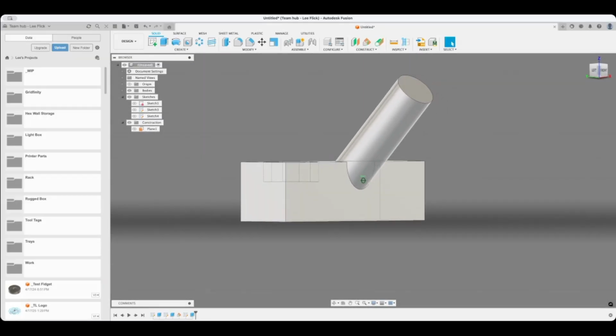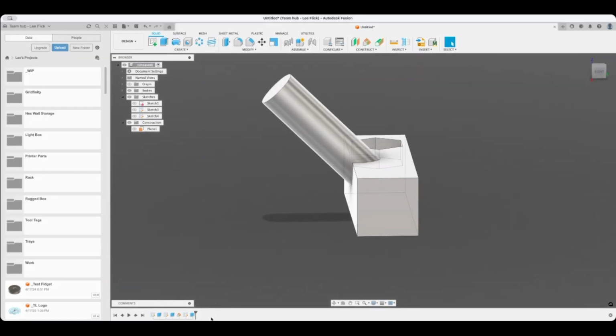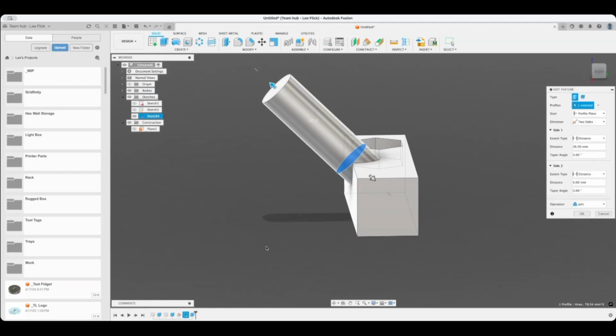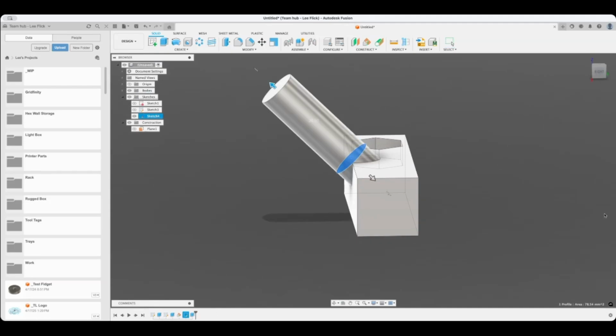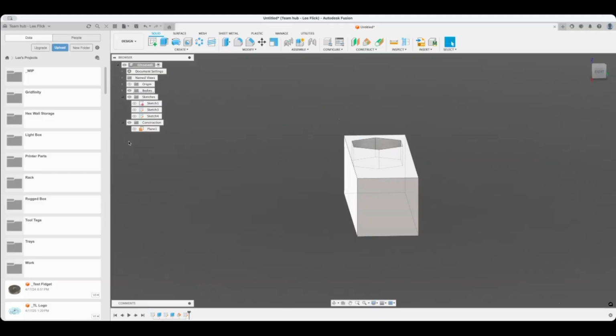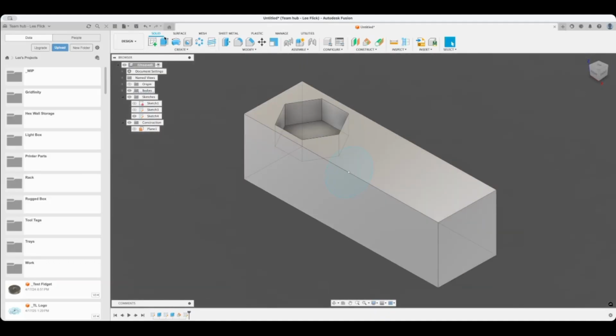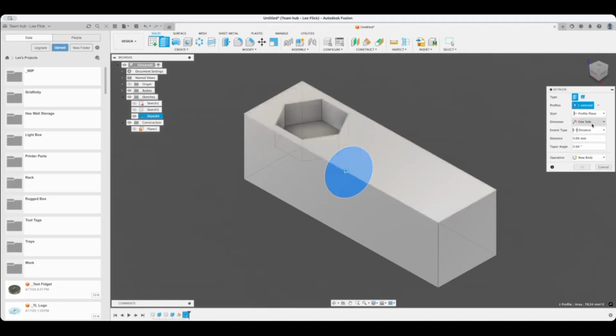Okay, can you back up and show me how you did that again? Sure. So we're in our extrude command. Here, let me back up completely. I have it on the plane and I have it all there. I just need to see how you got the two sides. Okay. So I hit my extrude. I hit my circle. I'm going to pull it out. I don't care how far. And then in the box over to the right where it says extrude, there's a box that says direction and says one side.